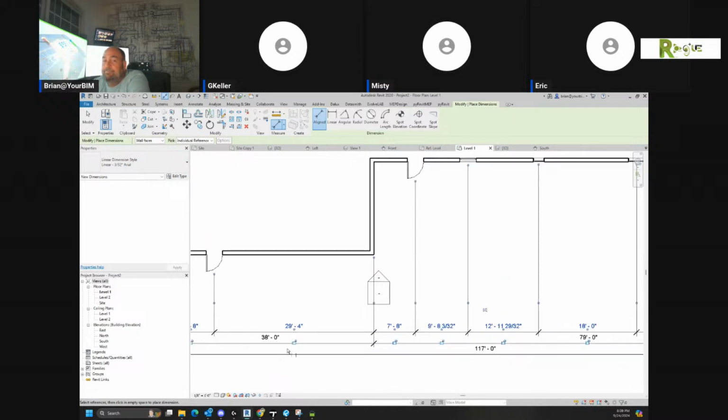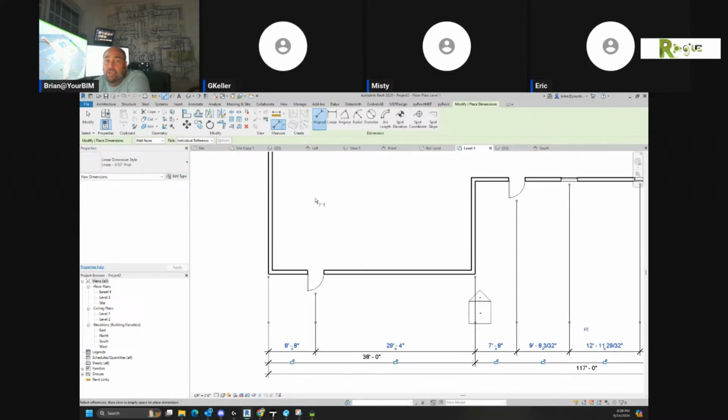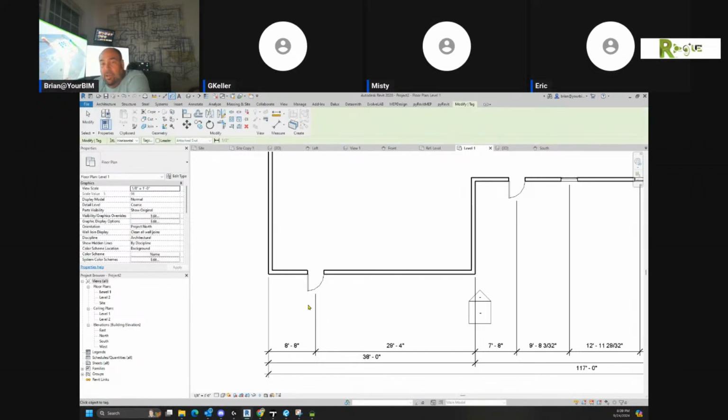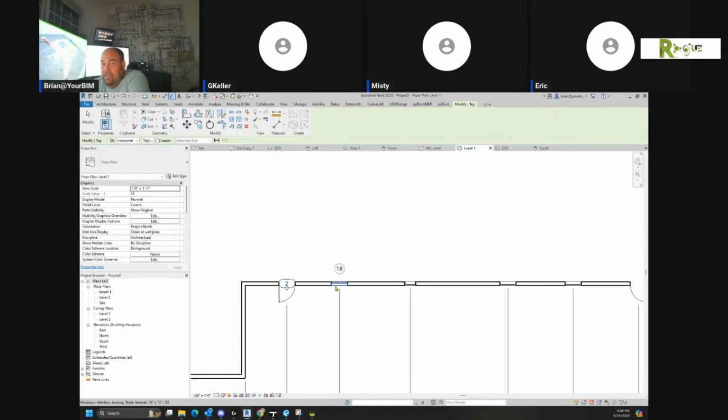All right. Then the next thing I told you to do was I wanted you to tag the doors and the windows. If we go tag by category, if you've started with the architectural template, you will have door tags and window tags.